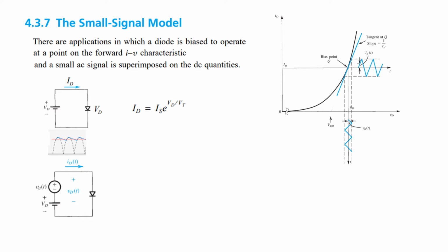Okay, so now our circuit can be represented as the DC voltage and the ripple voltage, or the AC voltage we can say, to give the correct picture. And so this voltage, now you can see across this, or across even the diode, is now small v and capital D, that is, AC and DC, a combination of these two, DC and AC. And similarly, the current will also change. Now, no more is it DC, it is a combination of AC and DC, so small i capital D.